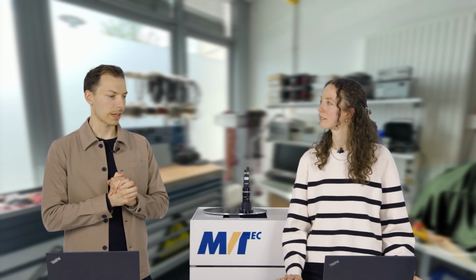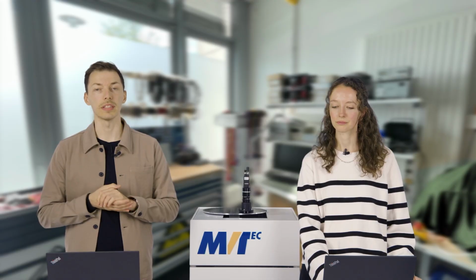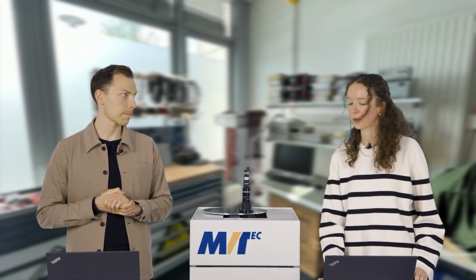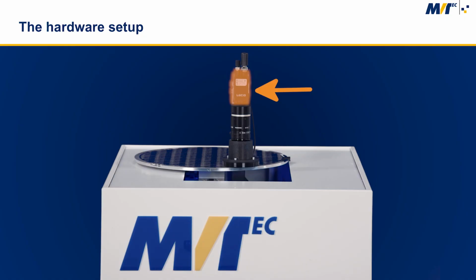Cool. So a question regarding this demonstration we always encounter on trade shows, for example, is about the hardware. People are always asking on which hardware the demo is running. Can you tell us a little bit about that? Yes, of course. So we can see here a 12-inch wafer lying on a plate that is mounted to an XY table. And this XY table makes it possible to move the wafer below the camera to ensure a thorough inspection. Up here we have a Lucid camera for high-resolution images, and down here a low-angle ring light to enhance the defect contrast.